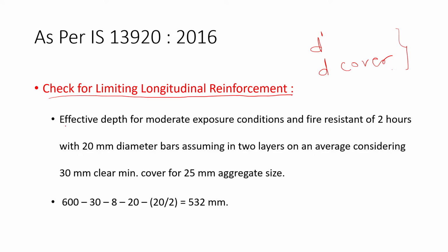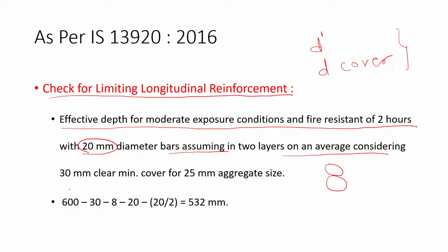So effective depth for moderate exposure condition and fire resistance of 2 hours, with 20 mm diameter bars assumed in two layers, on average considering 30 mm clear cover for 25 mm aggregate size, means my clear cover is 30 mm.